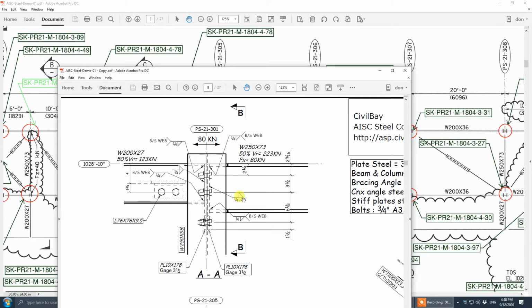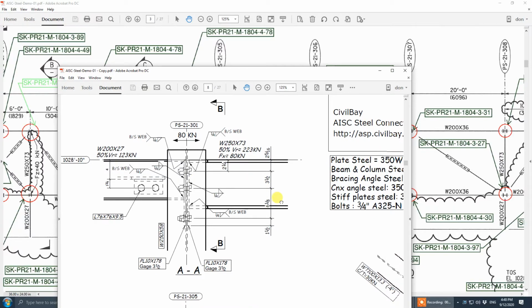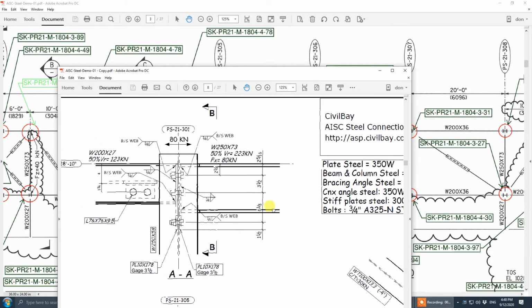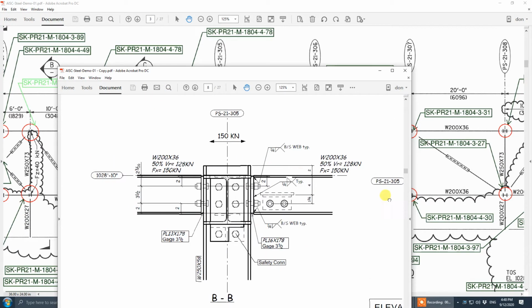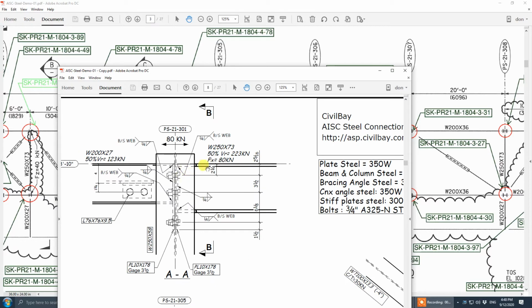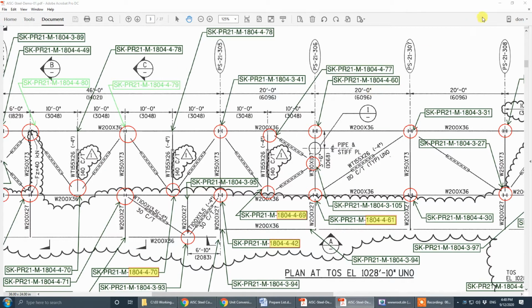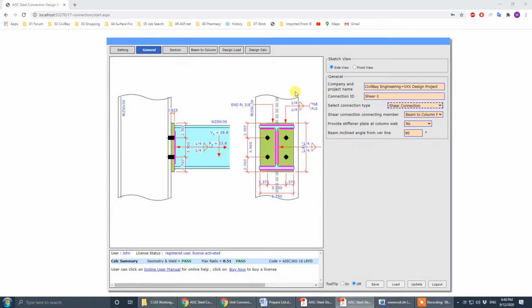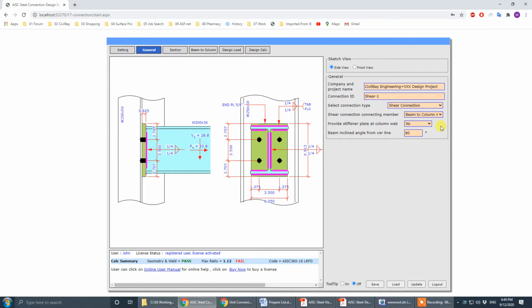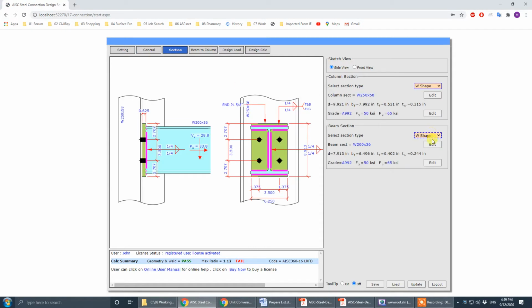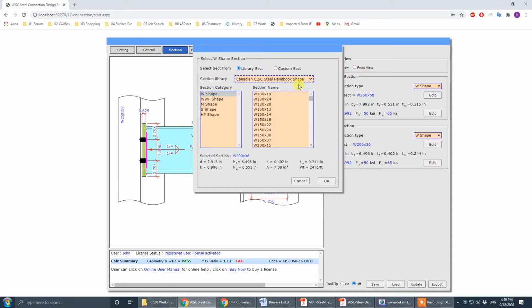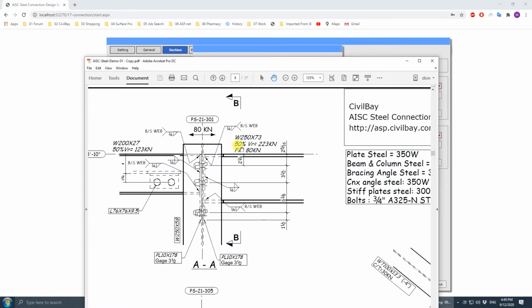This one to a v-axis, and the section BB. Where's section BB? Section BB is this one. All right, so move this out and minimize this one. Now column size is the same, but it's been changed to column web, and the section is being changed to 250 by...